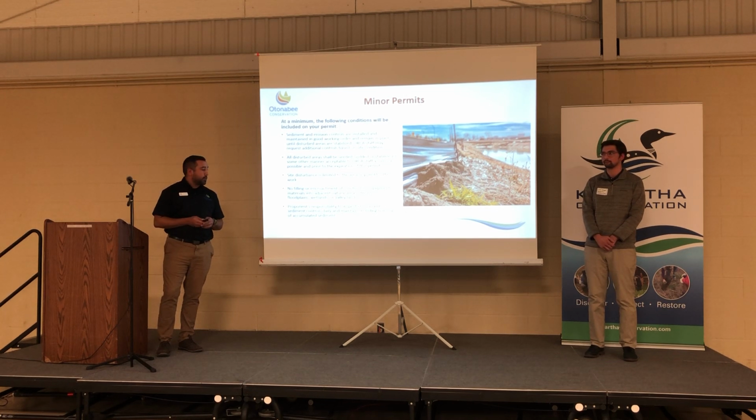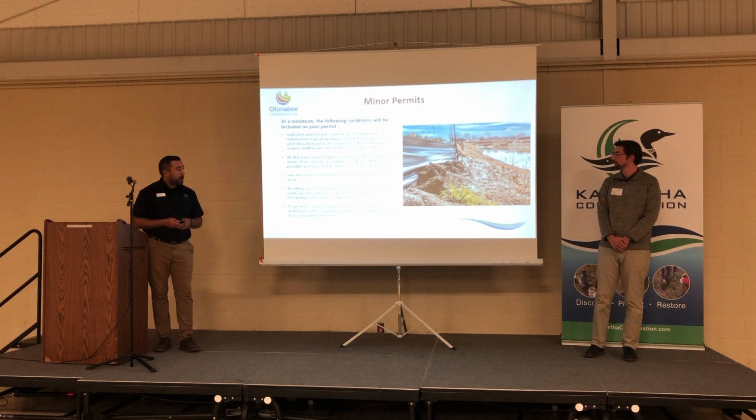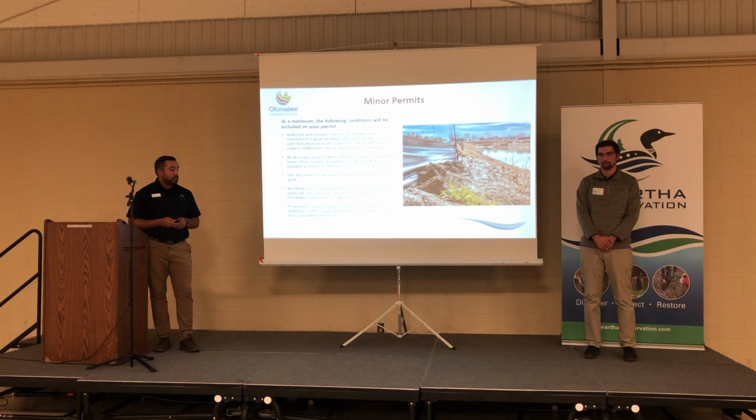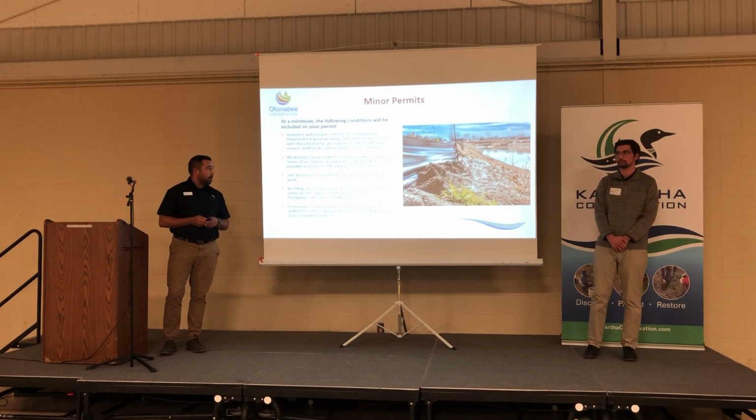any other regulated features. And also to keep in mind that it is the proponent's responsibility to inspect the erosion and sediment controls daily throughout the project and maintain them until the conclusion of the project. And this includes removal of accumulated sediment whenever it's necessary.